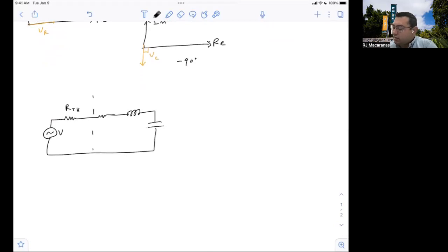And so this side is our load. This RLC branch here is our load, and it doesn't have any active components. It doesn't have anything that's supplying power into the circuit. If we only had this load, then power would just completely dissipate and go away. But on the other side, this is our source on the left, we have some kind of input, a voltage source that's constantly driving the circuit. We can reduce this into some Thevenin equivalent circuit. It wouldn't make much sense to reduce the load into some Thevenin since there's nothing that's supplying power. So this is our source, and we model it with some R Thevenin and some V Thevenin. I'm just going to call it VI for that input. And so this is the RLC of our load.